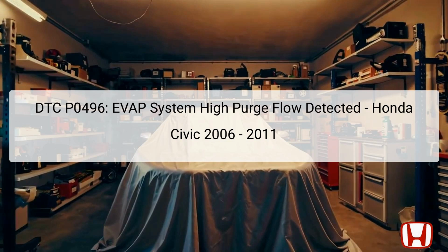To diagnose this issue accurately, it is crucial to first collect any freeze frame data available, as it captures the conditions during the fault occurrence. Additionally, any onboard snapshots should be reviewed to understand better the context in which the error arose. The entire troubleshooting process will guide you through narrowing down the possible causes, focusing on various components within the EVAP system that could be malfunctioning.